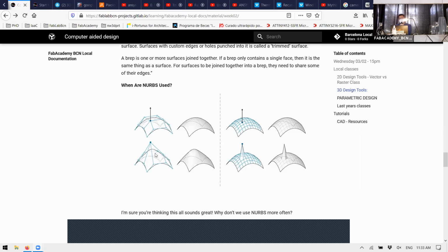For example, even if we visually see continuity, we are working with averages of curves at the end. It doesn't have a real location per se. Like this part of the surface doesn't exist. If I put a dot on that surface, that dot will not be exactly defined. It's being averaged all the time by the computer, it's calculated.